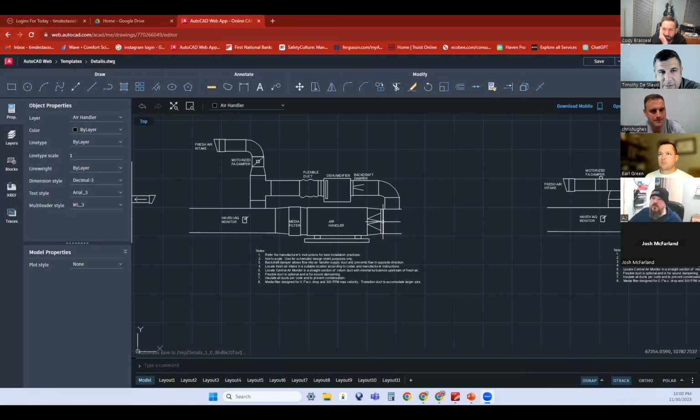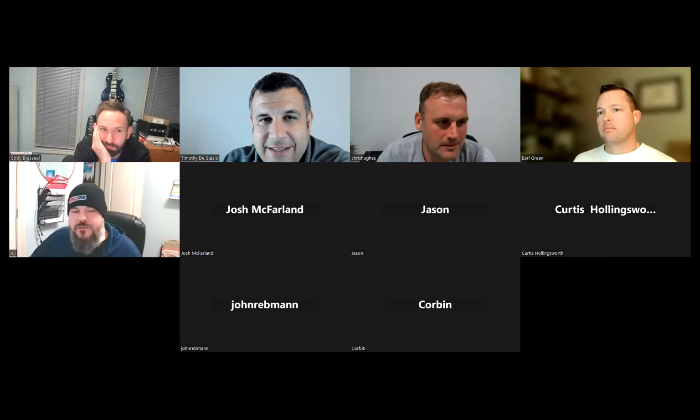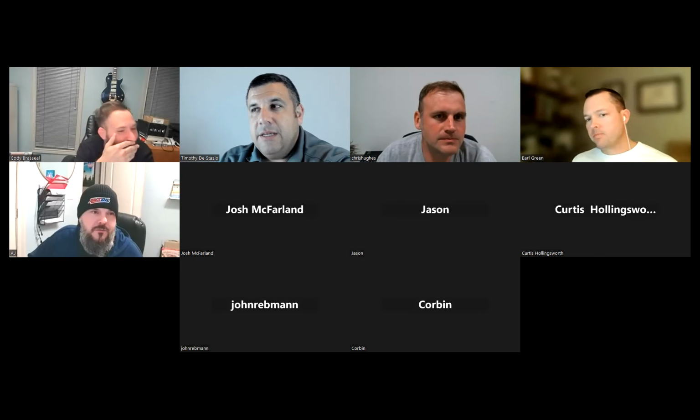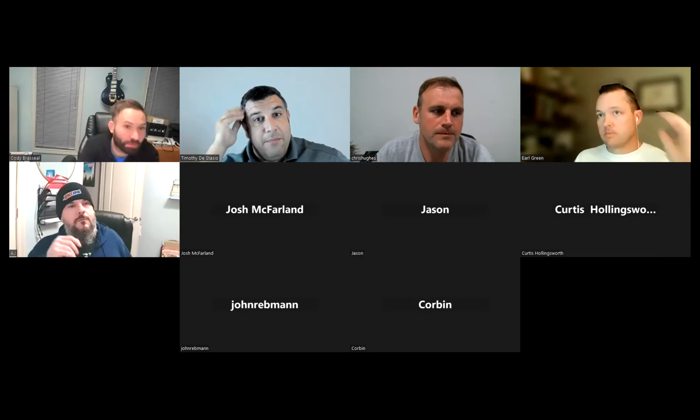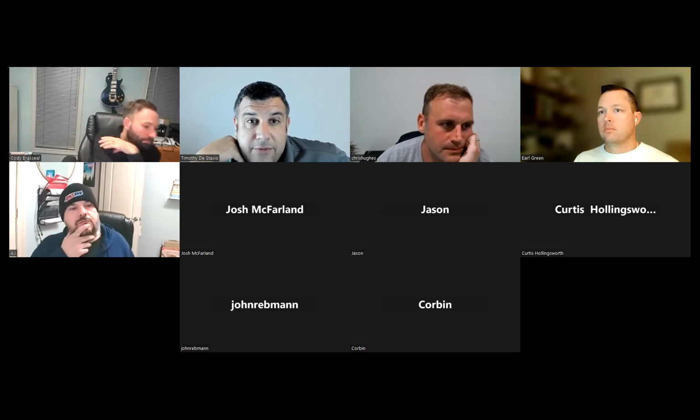Do you calculate the pressure loss on that fitting when you do your Manual D? That's exactly right. Tim, do you add the CFM from the dehumidifier to your total system, or do you just dump it? I haven't. There's not a great way for me to model it in RightSoft. Maybe somebody else is better.